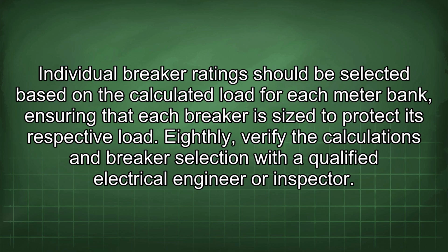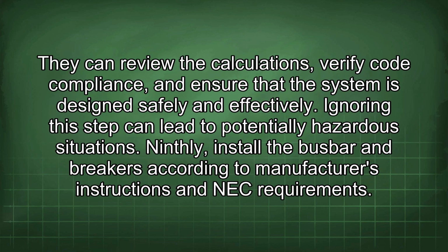Eighthly, verify the calculations and breaker selection with a qualified electrical engineer or inspector. They can review the calculations, verify code compliance, and ensure that the system is designed safely and effectively. Ignoring this step can lead to potentially hazardous situations. Ninthly, install the busbar and breakers according to manufacturer's instructions and NEC requirements.